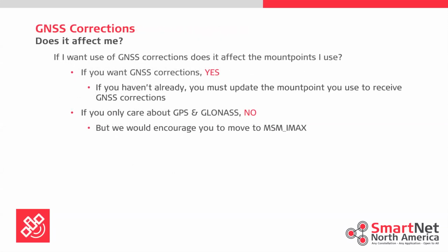So does it affect me for GNSS corrections? If you want to use a GNSS correction mount point, then yes, the GNSS mount points affect you. If you haven't already, you must update the mount point to be able to receive GNSS corrections. So if you want GNSS corrections, you've got to be on one of the MSM mount points. Have to, no questions. So please update. If you only care about GPS and GLONASS, then no, you don't have to update. But we would encourage you to move to MSM IMAX. We're not going to cut them off. We're not turning them off. But we encourage you to start making that move to get the newest whiz-bang GNSS features should you need to.